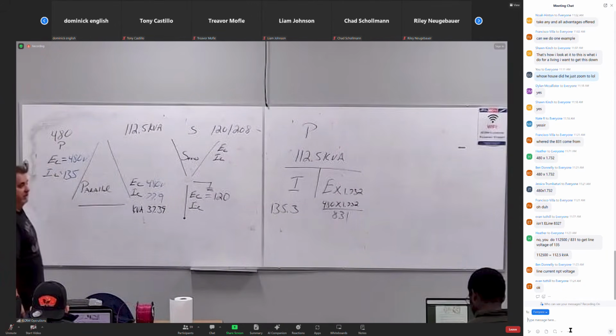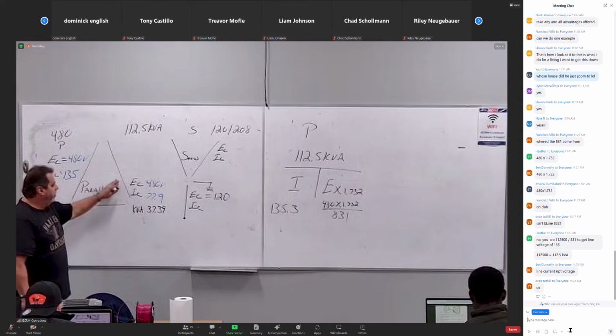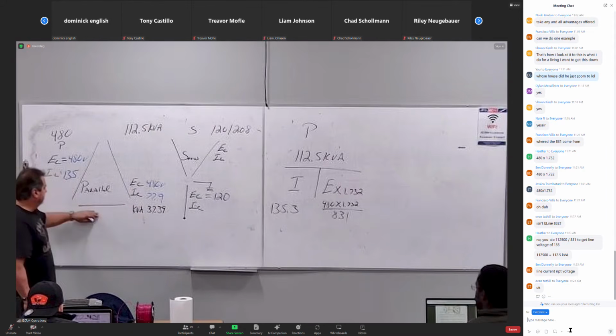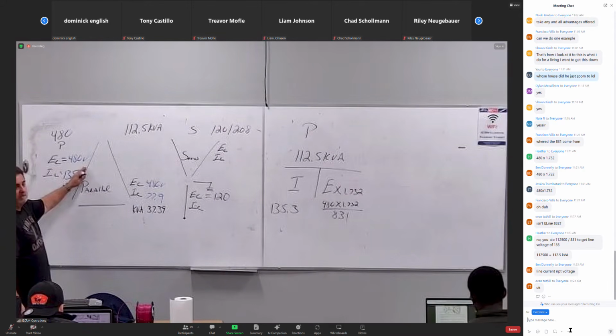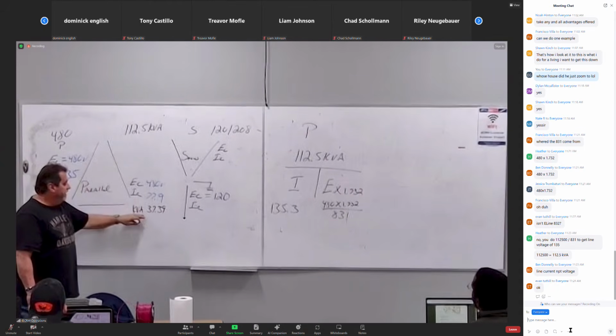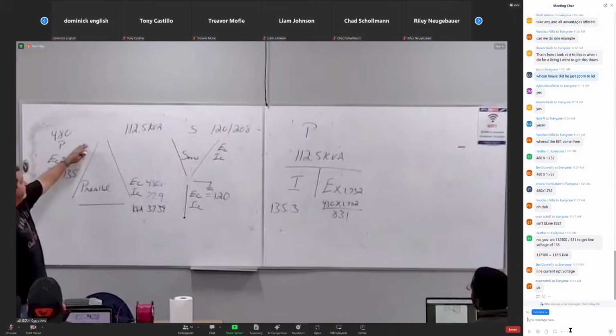37.39 kVA. In any circuit, whether it's delta or Y, coil power is additive. That load plus this load plus that load, guess what it equals? That load. You know how else to find how much each kVA is worth in your transformer? Take your total kVA and divide it by 3.